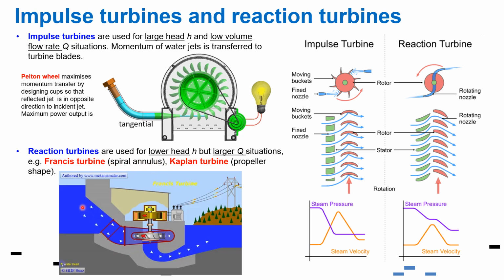It means that coming from the penstock here, it goes towards a sort of round casing, and then it will go radially into the turbine to rotate the turbine blades, and then go out into the other side here. So this turning here is going radially, and then there is an axial part as well that goes out.